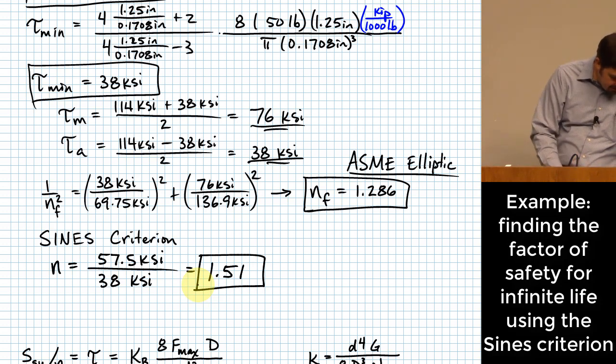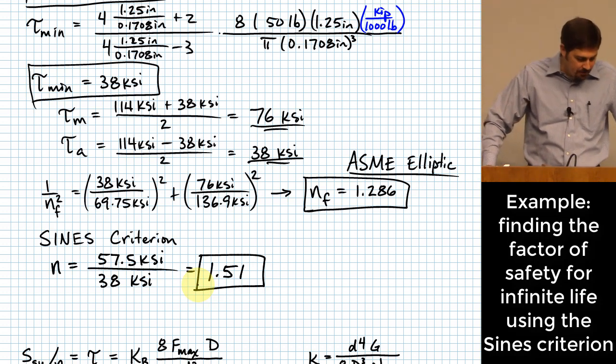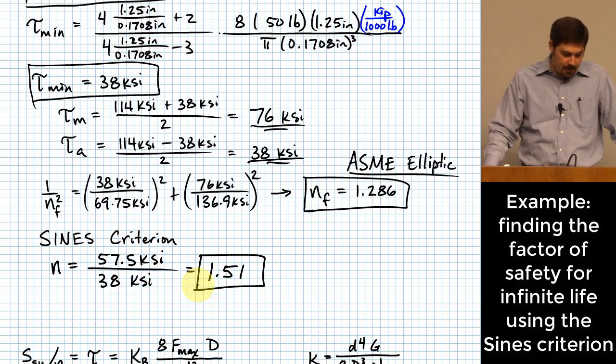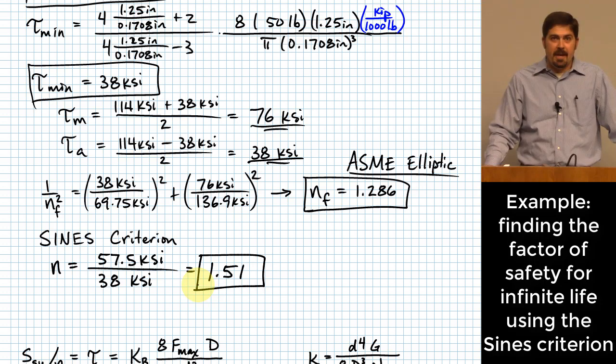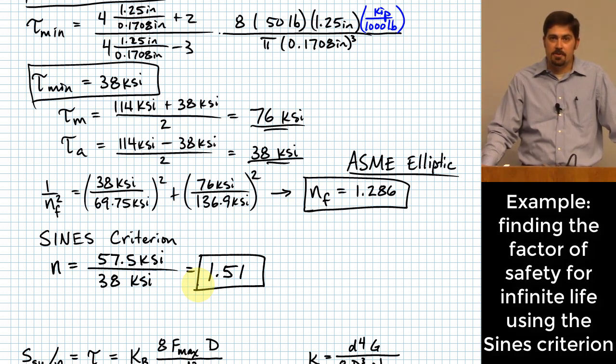An extended study of available literature regarding torsional fatigue found that for polished, notch-free cylindrical specimens subject to torsional shear stress, the maximum alternating stress that may be imposed without causing failure is constant and independent of the mean stress in the cycle. All right, and it's basically saying springs, many times anyway, exhibit those characteristics, and so the Sines failure criterion is often okay to use for that purpose.